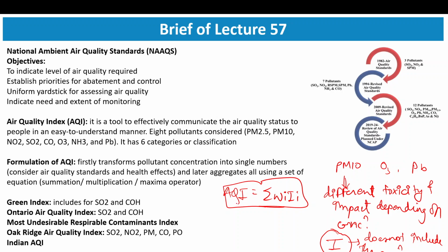So depending on the region, you have different ways of identifying AQI. So you do weighted average, W_i I_i for each of the pollutants. Or the one which will have the highest I, it will determine AQI. So that is the method which is followed in India. While you can look into what other countries and what other regions follow for AQI measurement, right?